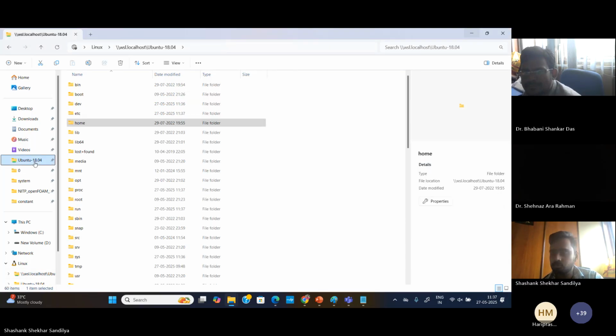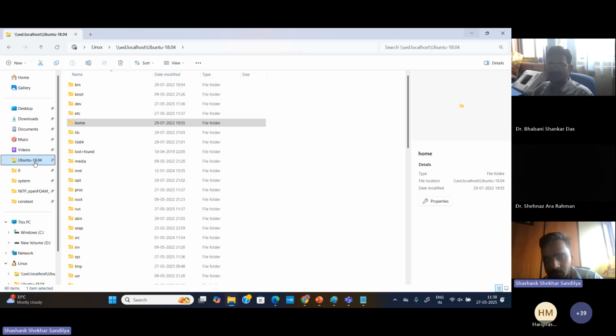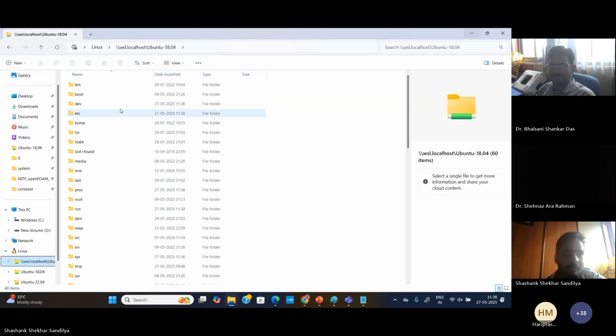Okay. So yesterday we shared an installation guide in which, if you go through it, you find that we require three things for simulation using OpenFOAM. The first, Ubuntu, is required for execution of the codes, and the other is the OpenFOAM software. It is inbuilt into the Ubuntu. And the other is ParaView, which is required for post-processing of the software. In my system, it has already been installed. So when I open the Ubuntu, it is visible.